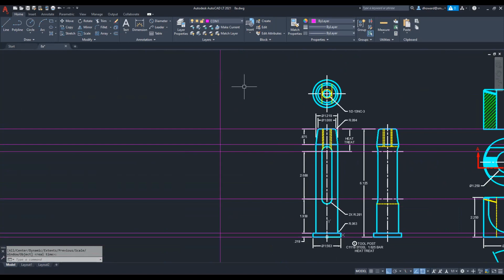All right, so what is 1/2 of 27/64? It would be 27/128. You just double the bottom, right? So if you want to do that by the book, offset, O, enter, 27 divided by 128. There it is on both sides. So that is the internal hole.